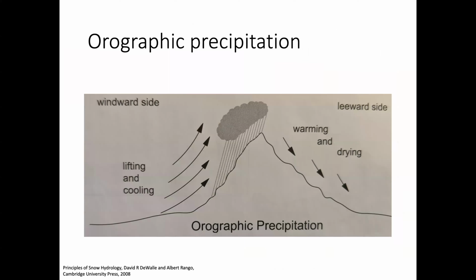While snow occurs over large expanses, orographic precipitation occurs in the presence of mountain ranges, which lift the air. As the air is lifted, it cools and expands, dropping precipitation. As the air mass reaches the top of the mountain and it can expand to lower elevations, it warms and dries, releasing less precipitation. This process depends on the wind speed, the amount of water, the slope, and the orientation of the wind relative to the mountain. The two different sides of the mountain are called the windward and leeward sides. Warm fronts, cold fronts, and lake effects are other examples of snowfall formation that may affect the amount of snow.